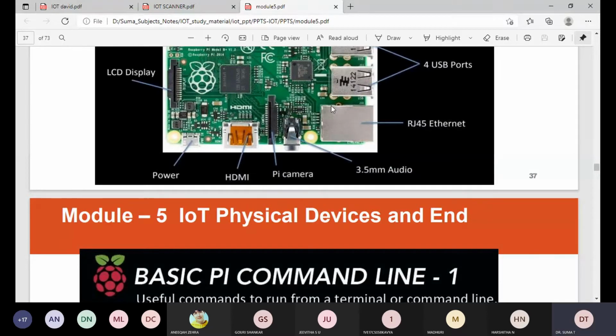We have the processor: the Broadcom BCM2835 SoC used in the first generation Raspberry Pi. This is somewhat equivalent to the chip used in the first generation smartphones. Its CPU is an older ARM version 6 architecture. So that is why they use a 700 megahertz ARM1176JZF-S processor.